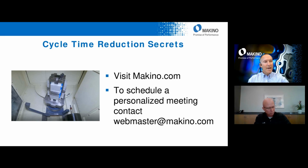And then another question we have, I know I hear some customers talk about how important it is to keep as much coolant in the machine as possible, right? Sometimes you have issues with chips going out through the chip conveyor that you can have a lot of coolant loss through that. And so the person is asking, since the tool change occurs soon after the coolant turns off, is there a concern of more coolant being carried out of the work zone and into the ATC? I guess in general, it's always a concern. You have to just monitor each tool change to see if you're getting that.